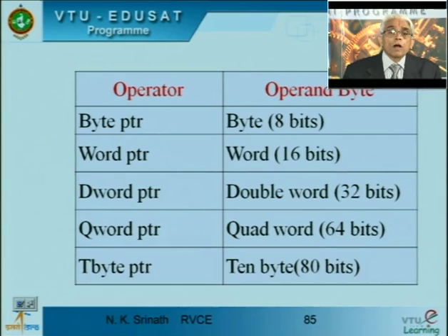Similarly, we can also talk about byte PTR, word PTR, double word PTR, quad word PTR, 10 byte PTR, saying that you are now considering the data as either 8 bit, 16 bit, 32 bit, 64 bit or 80 bits.